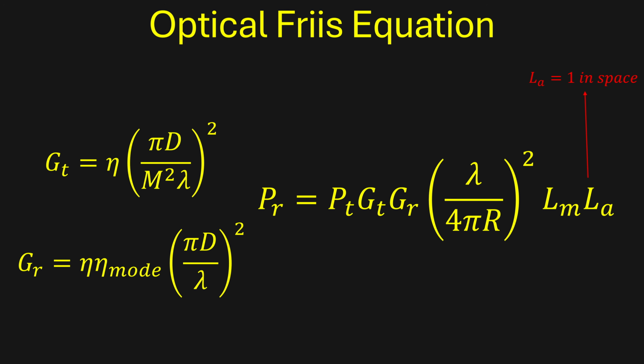So, since we can always use the far-field diffraction math for these ranges, the gain formula is very similar to RF. The difference is the aperture fill factor, the beam quality factor of the transmitter, and the coupling efficiency of the receiver. That represents the losses along the transition between the telescope and the insertion into a single-mode fiber, and that will only apply to coherent detectors. You could treat these terms as separate losses, but here I'm just including them within gain. The free space path loss and the rest of the Friis equation is the same.